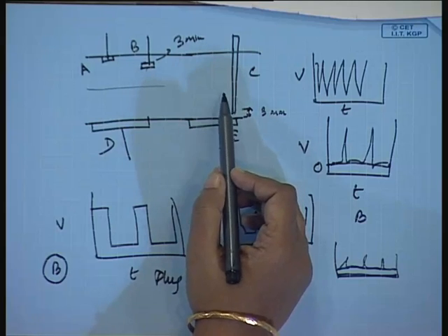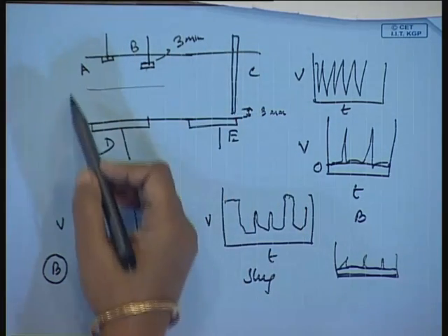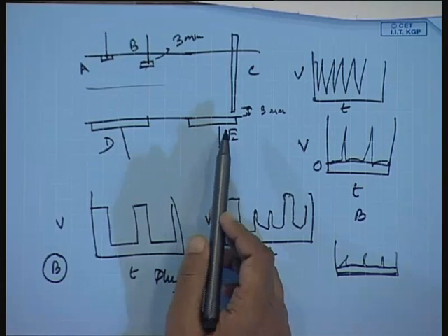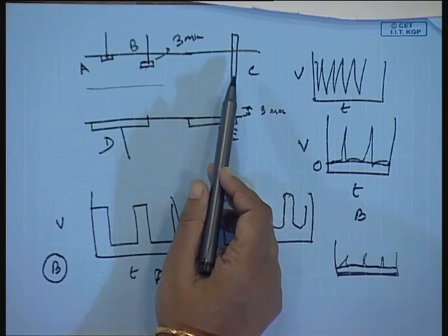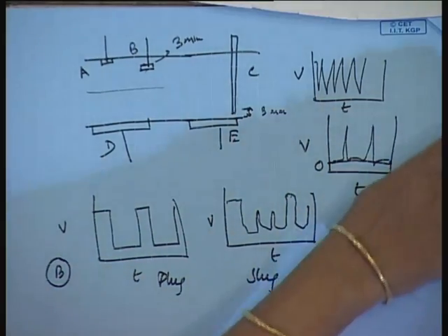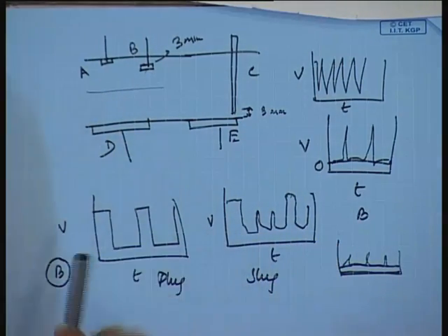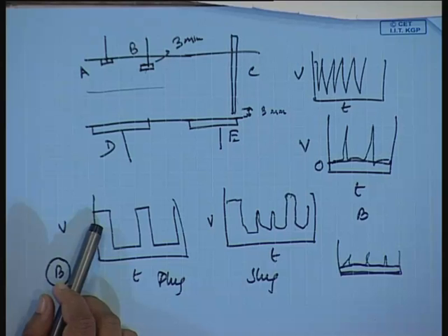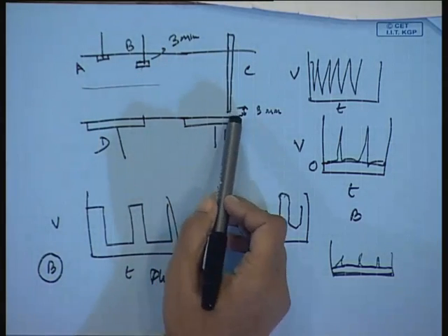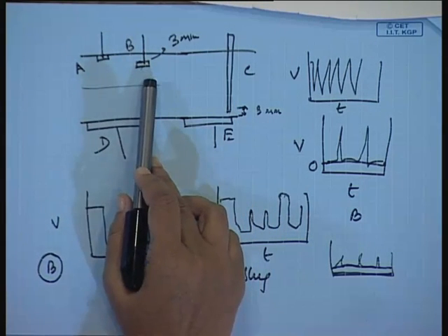So, remember one thing: since it is a very cheap technique, you can use different designs, and from these different designs we can differentiate between the different flow patterns. Now, suppose I tell you to differentiate between wavy and smooth stratified, then in that case you just need probe C; you do not need the other probes.